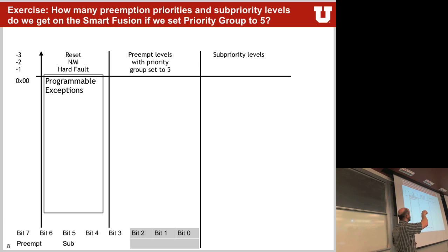You can't change the priority of the NMI. You can't change the one from the hard fault. They are predefined. But for any other interrupt source, be it from the bus system, for example, there's a bus handler, a bus reset vector there, or if it's a peripheral, they will be programmable by you. But then a silicon manufacturer or somebody who gives you his Cortex M3 can decide not to implement all 8 bits of priority, which will then limit you again.